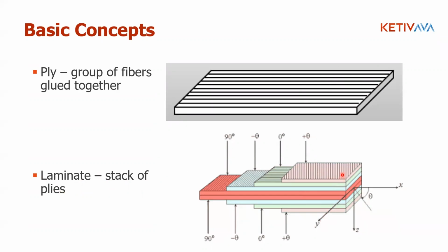Okay. The amount of material, the thickness of the ply, has to be determined, because that's obviously going to determine how stiff this layer is going to be. And you need to define the orientation of your ply. Okay, because typically these plies will be orthotropic material, and so the stiffness in different directions is going to be different. So that's why the orientation of the ply becomes very important.